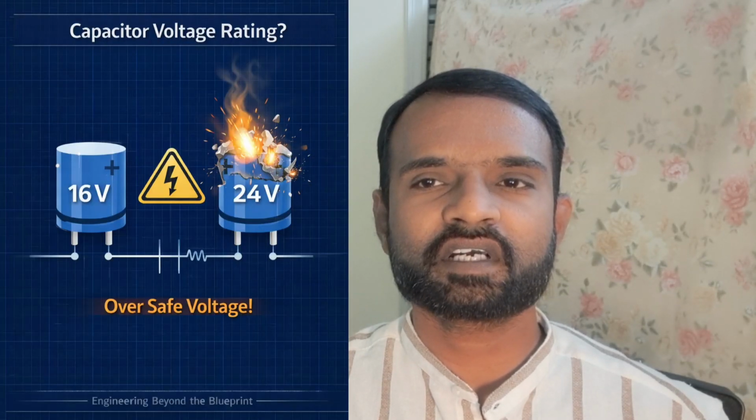Why does capacitor value change? Capacitor value changes due to the temperature and DC bias effect. Example, 10 microfarad X7R becomes 5 microfarad at rated voltage. And understand the difference between three dielectric materials called C0G, X7R and X5R. C0G is stable and accurate, whereas X7R is good in balance and X5R is smaller and less stable. Example, trimming circuit uses C0G.